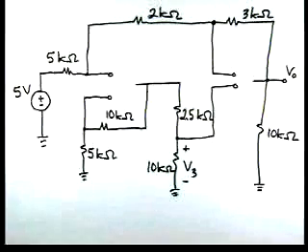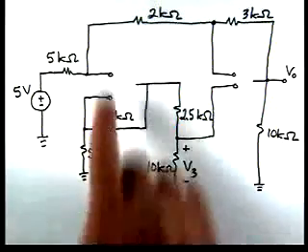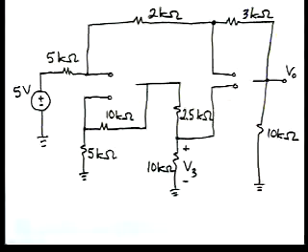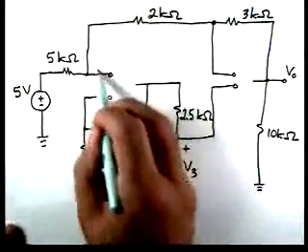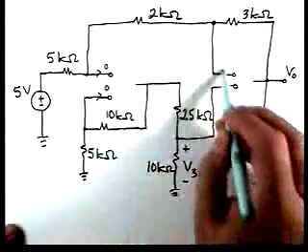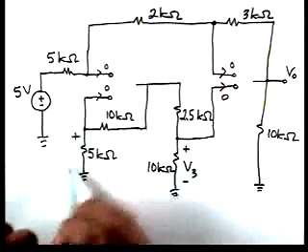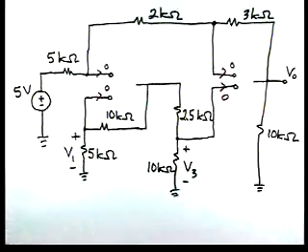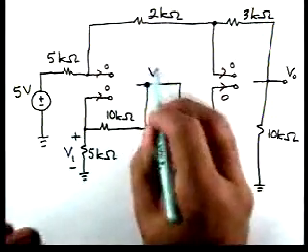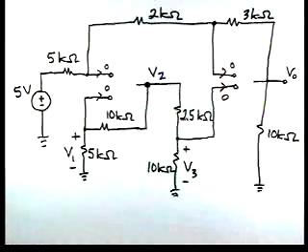So here's our circuit. You can see when we substitute the op amp model in, that's where the op amps were. We can see the current's 0 on these terminals. We enforce that by showing an open circuit. Now let's define this voltage as V1, and I'm going to define this voltage as V2.